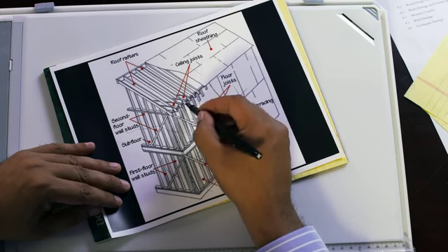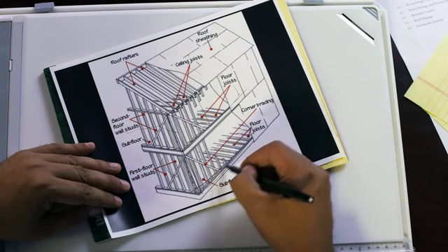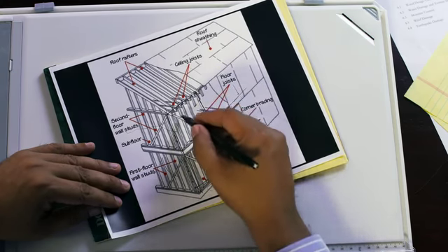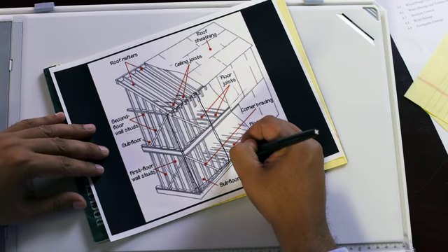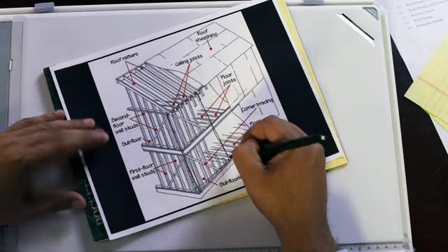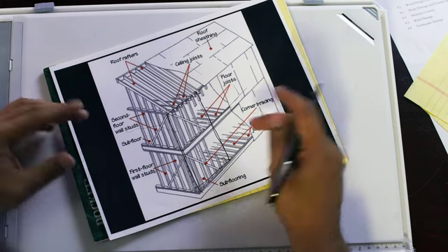If, for example, let's take this design. Let's say that my architect wants to create a bay window here, and he wants to have the height of the window going up 2 stories. Yeah, you can do it. I didn't say you can't. You're just not going to be able to do it in wood. You'll have to put a steel column over here and a steel column over here. So it can be done, but then you've got to go with a different material. You can't do it with wood because it's too much.